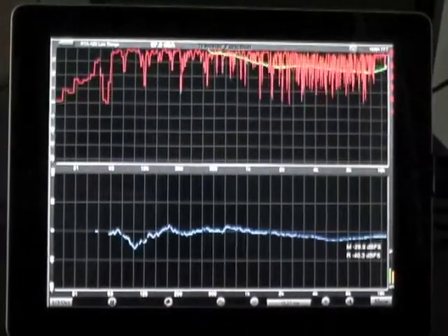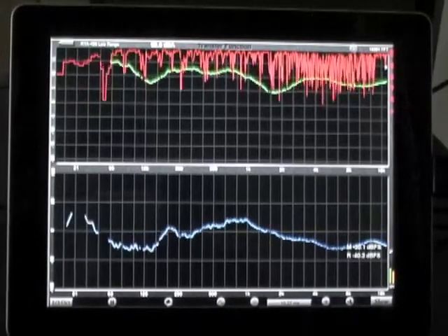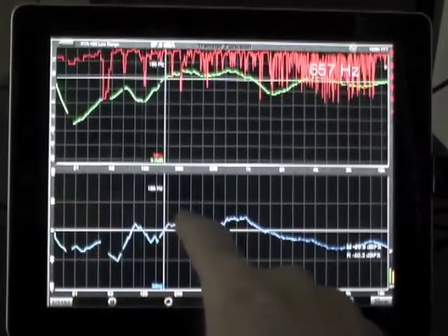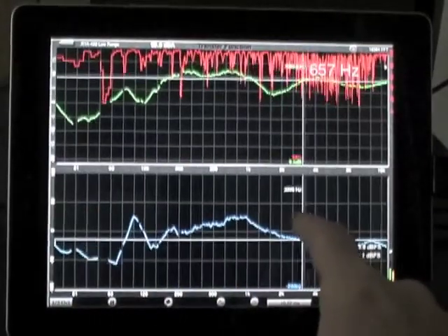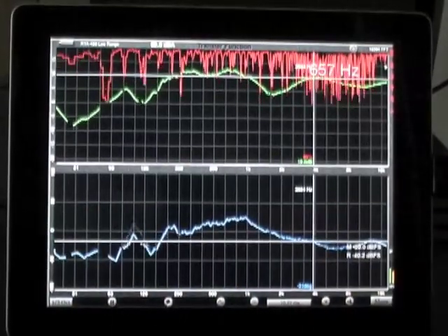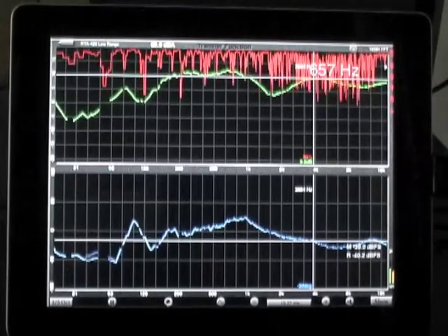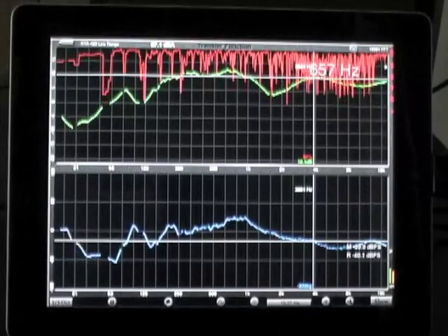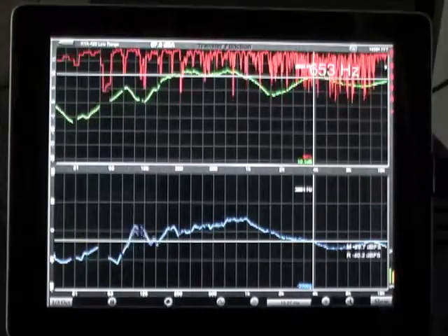Comparing this graph to the one produced using music, the main difference is that we now have plots that cover the whole spectrum. This is because pink noise is a full bandwidth signal and it contains all frequencies from 20 Hz to 20 kHz. The overall shape of the curve, however, is the same, showing how transfer function results are independent of the test signal.